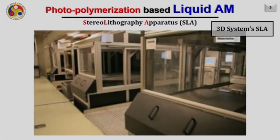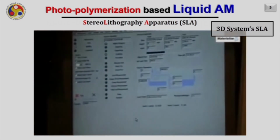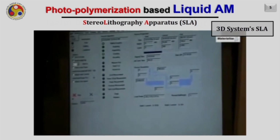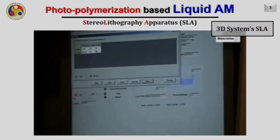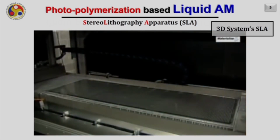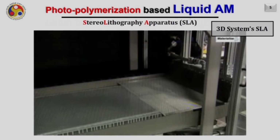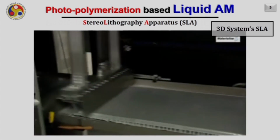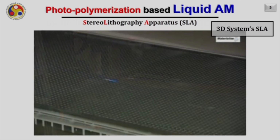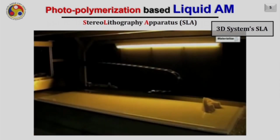So this is a typical 3D Systems SLA machine that you are seeing here, and this is the graphical user interface for the machine. Here one can put in appropriate process parameters and then the machine can operate appropriately. What you can see, these moving blue dots, are nothing but the laser beam. After scanning a layer, as you have seen, a recoater passes over and removes the excess material. The process repeats itself and builds the part completely. Then later on, the part comes out like you are seeing here now.